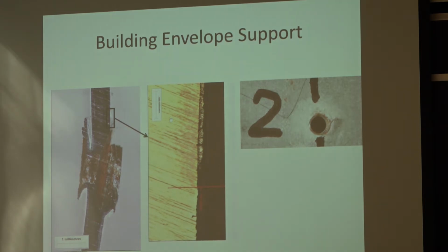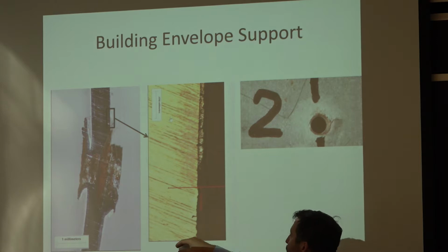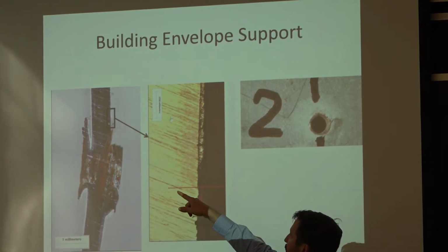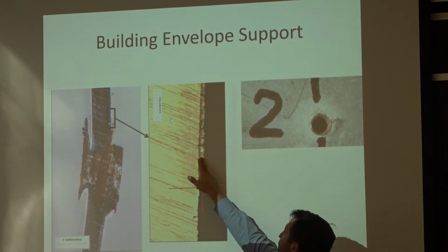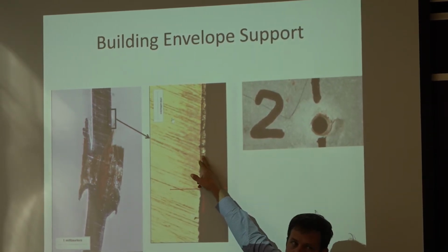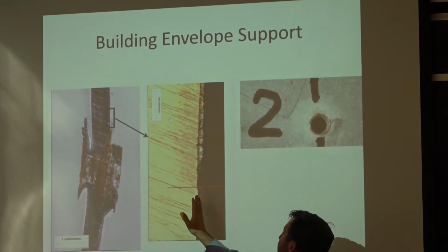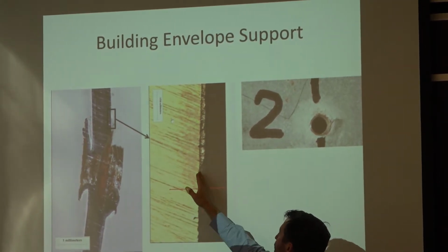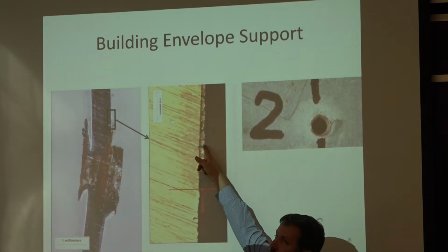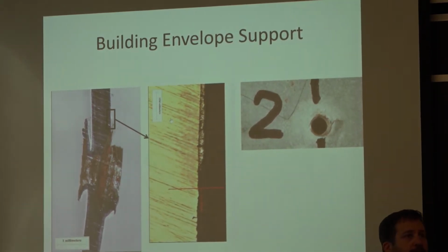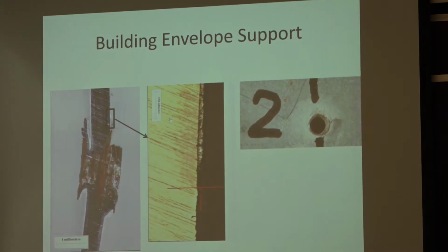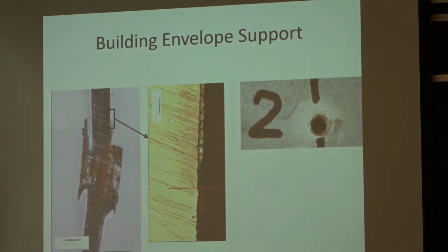What we're looking at in the middle image is approximately where the hole is on the sheet. I put a little square there. And then you can see you don't have any of that white layer, which is the galvanizing, left near the hole. It's all gone. And then it's the original thickness after a certain distance. That distance turned out to be about a quarter of an inch or 6 millimeters, something of that order. If you want to think about it simply, it's kind of the size of a big droplet.